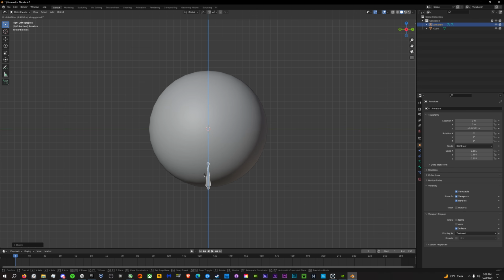And you don't want it all the way down or too close to the end, or it will try to make a weight there. So then we're going to switch to edit mode with Tab, press E, press Z, move that one to the center, then press E again, Z, move that one up a bit more, then press E again one more time, move that one up again.